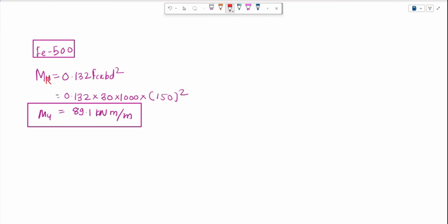If you want to know about under reinforced, over reinforced and balanced sections, I have already prepared a video on it. You can have a look at that in order to clear your concepts. Once you do it, it will show you what's the moment capacity that you are getting for this particular value. And you can equate this particular moment of resistance with your equation with respect to force in tension side multiplied by lever arm to get the area of tensile steel that is required for this particular moment. So now the ultimate thing that we need from this particular calculation is your moment of resistance capacity.